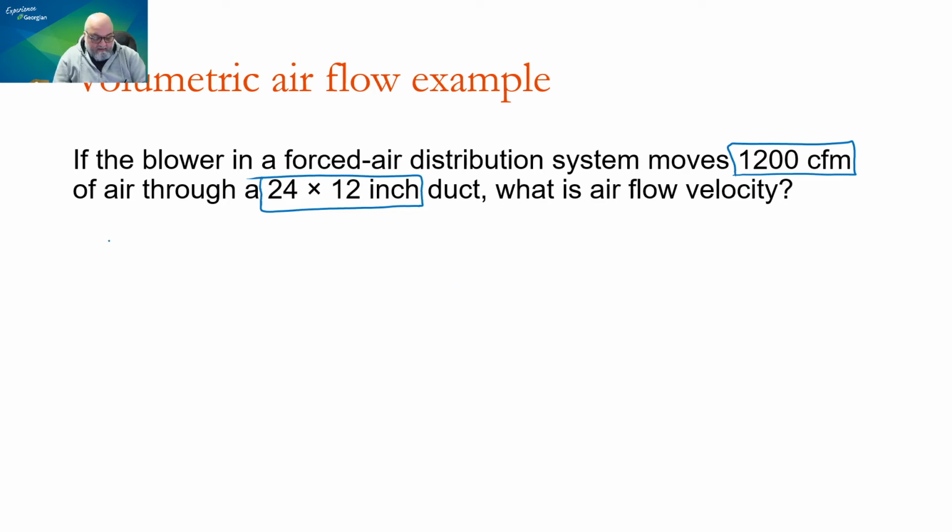Okay, again, velocity equals airflow in CFM divided by duct area in square feet.